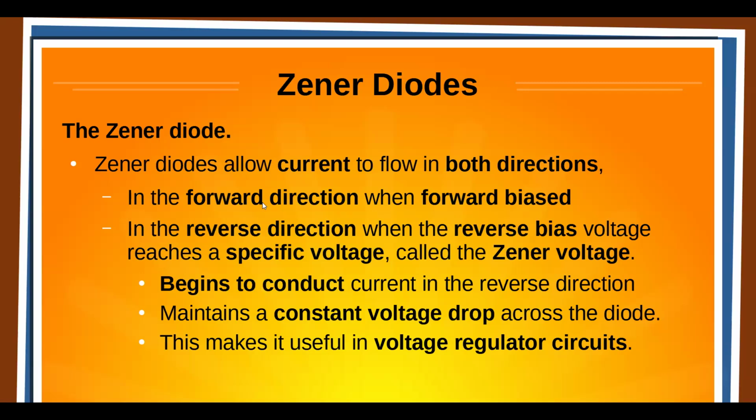So a Zener diode takes into account the effect that when it's reverse biased at a certain voltage, it will avalanche over. I think the guy that discovered that was named Zener. I'm not sure, but it's called the Zener effect. And they can manufacture diodes where they control that Zener voltage precisely, so you can use them as a voltage reference. And in fact, it's very common to see it in a voltage regulator circuit as the reference voltage.